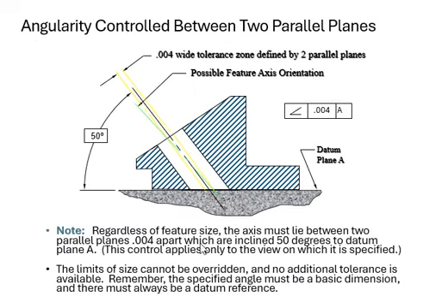Okay, and then we're going to exaggerate, and here is your datum plane. In order for us to see this datum plane, we're going to bring our tool, which is usually a gauge or something, and stick it in there to the high points of that surface on that part. The contact is going to be your datum plane, and we give it the name A. And we measure the angle from that axis to here, which is about 50, and it can vary about 0.004 plus or minus up and down.